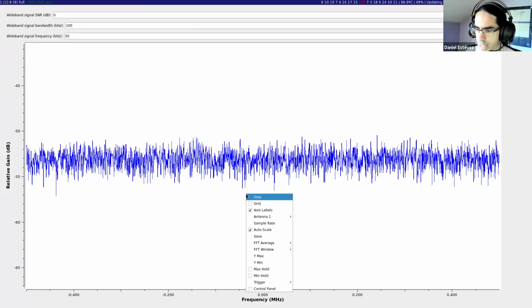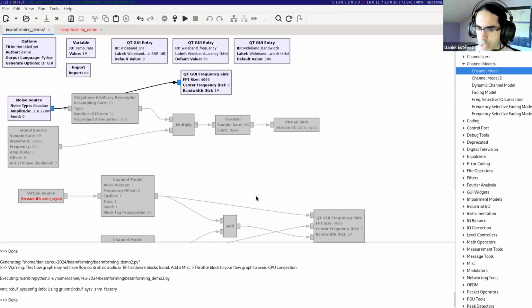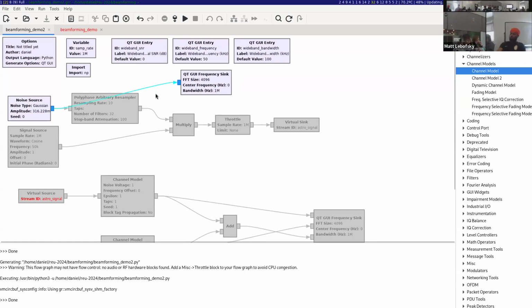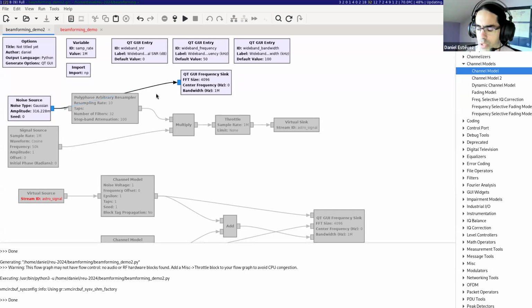The reason for this is that if you generate random Gaussian variables and each of them is uncorrelated, so here it's a stream of samples, all of them independent random Gaussian variables, then if you look at that in the spectrum, it will be flat. If I don't want the spectrum to be flat, I have two options. One of them is to introduce a filter, such as a low-pass filter, and that will introduce correlations between the random variables because a filter is doing sums, essentially.